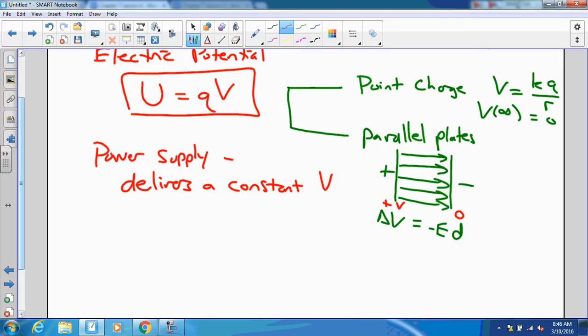So here we go. I've got a 13.86. Now I'm going to connect plus to minus, and when I do, a large amount of current should flow, but look at this. See there? The light just turns off, and that's because the power supply recognizes that it can't source as much current as I want it to. Look at the little indicator light right there. See? Goes off.